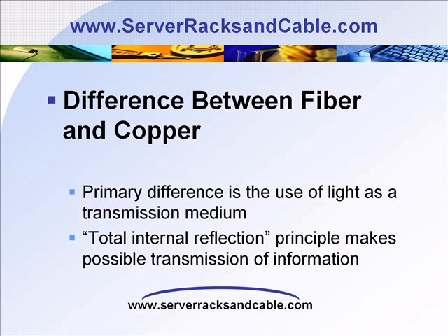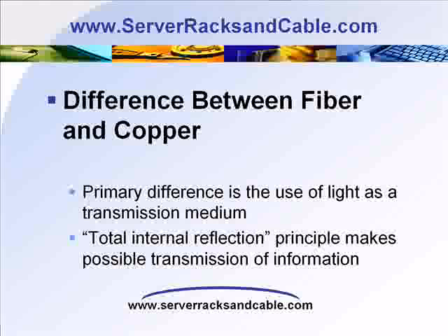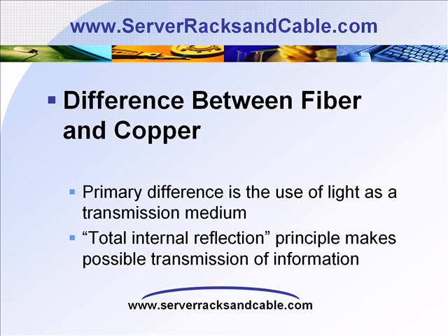A light source near to infrared wavelength of 850 nanometers is used for shorter lengths, and 1300 nanometers for longer distance on multi-mode fiber. While on single-mode fiber, light of about 1300 nanometers is used for shorter distances and 1500 nanometers for longer distances.